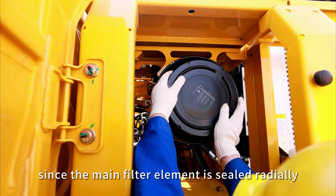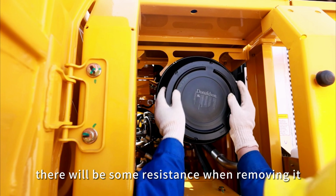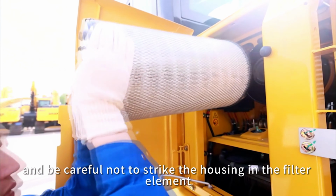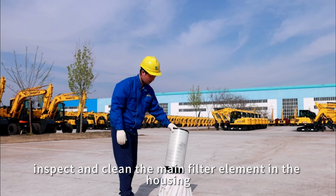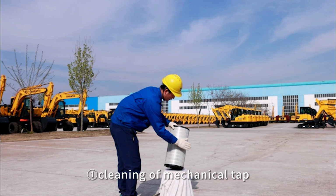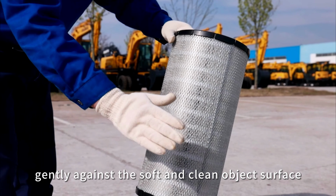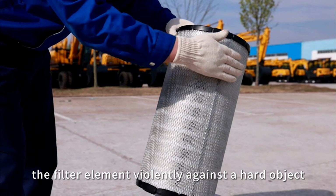Since the main filter element is sealed radially, there will be some resistance when removing it. Therefore, it shall be pulled and rotated at the same time, and be careful not to strike the housing and the filter element. Inspect and clean the main filter element and the housing. 1. Cleaning of mechanical: tap the end of the main filter element gently against a soft and clean object surface. Do not impact or strike the filter element violently against a hard object.